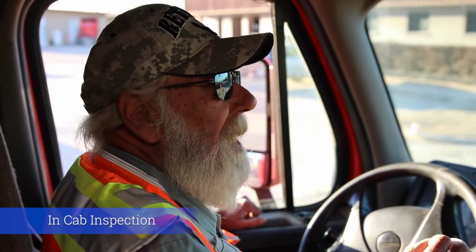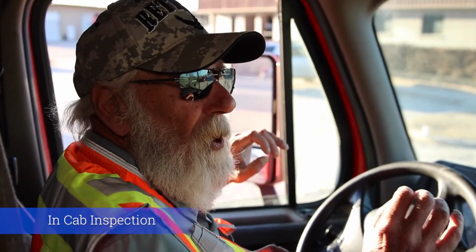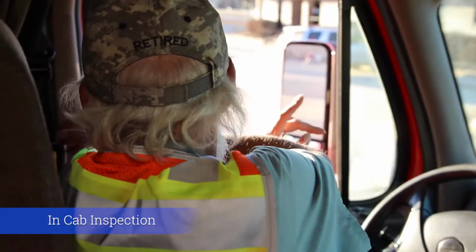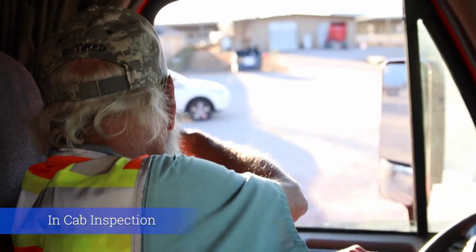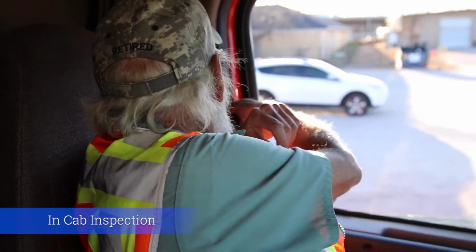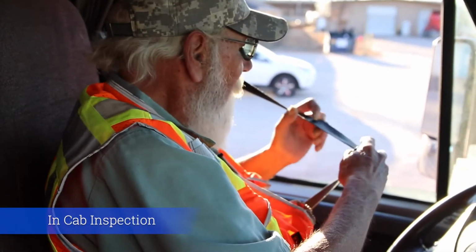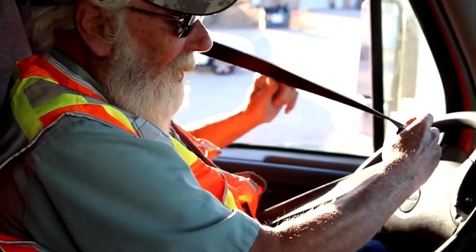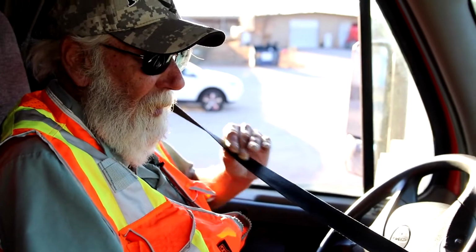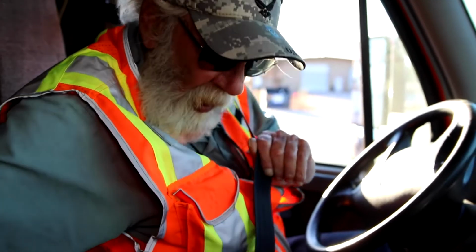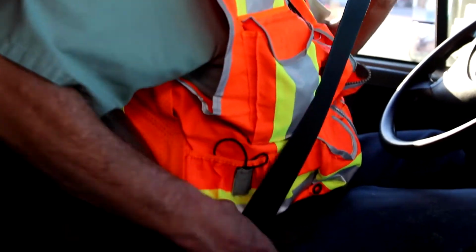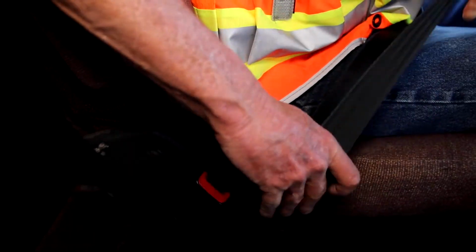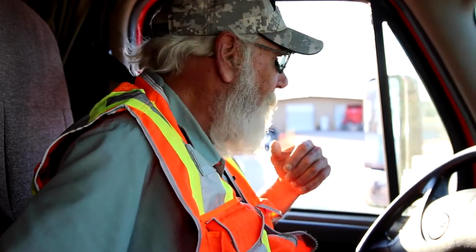Okay, this is your in cab now. I always start with my safety items first. So the first thing is your seat belt. It is mounted securely to the B-pillar of the truck and to the floor. Pull the belt out, inspect the webbing, the belt itself. No abrasion, bulges, and cuts. Come to your latch. It latches and unlatches freely with no problem. The latch itself is mounted to the seat and to the floor.